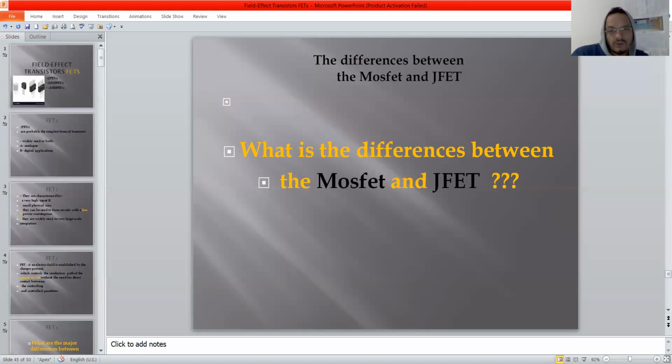What will happen? Let's take a look at these two different images. Here, the middle was full of electrons, and the depletion region has a huge similarity with the no bias condition, with no power source. But here, after we applied the drain source voltage of 2 volts and more, what will happen?